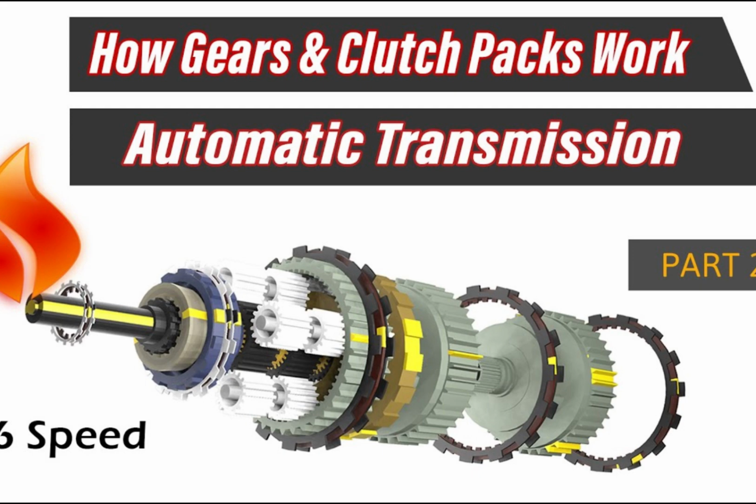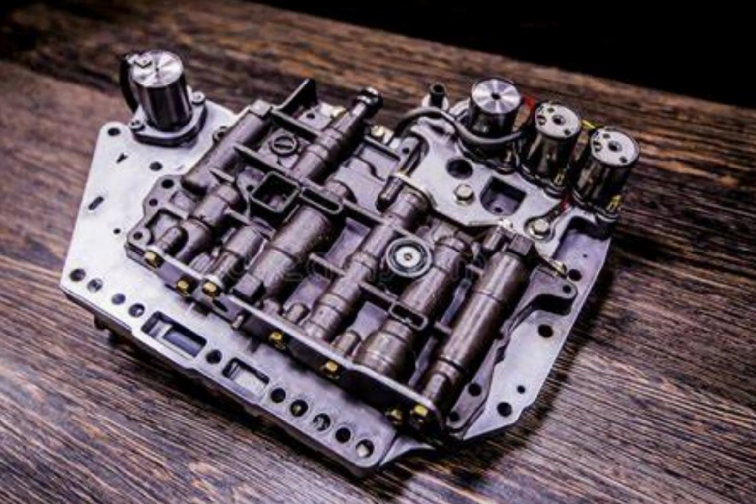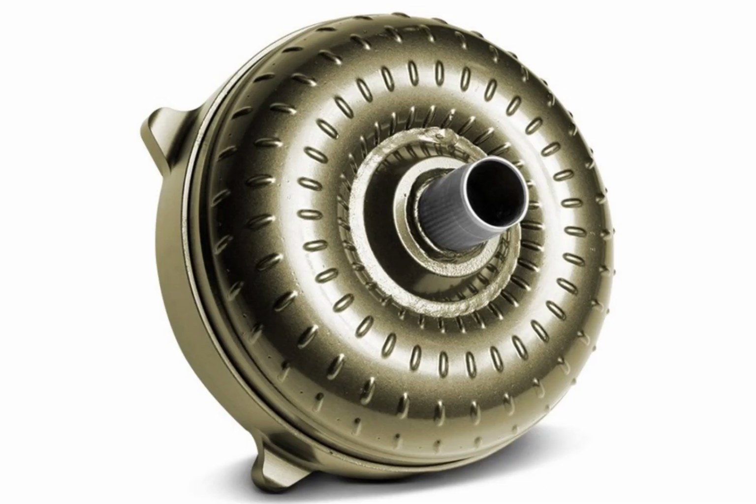Critical parts to handle with care. Valve body: extremely sensitive. Dirt or improper assembly can cause failure. Clutch packs: fragile and must be replaced if worn. Seals and gaskets: ensure proper fit to avoid leaks. Torque converter: check for wear or contamination.